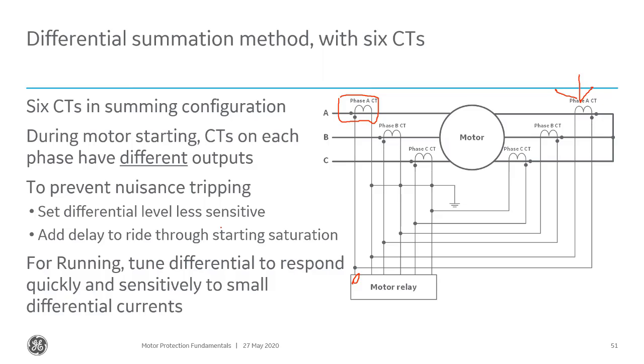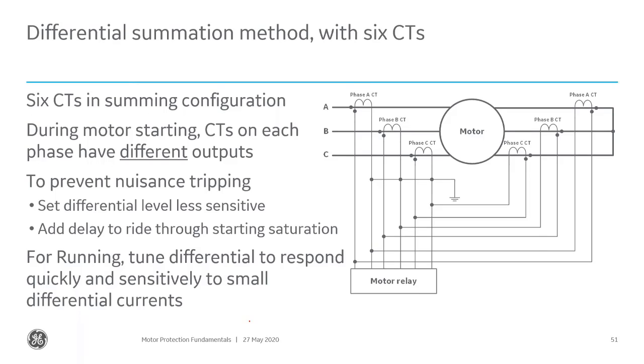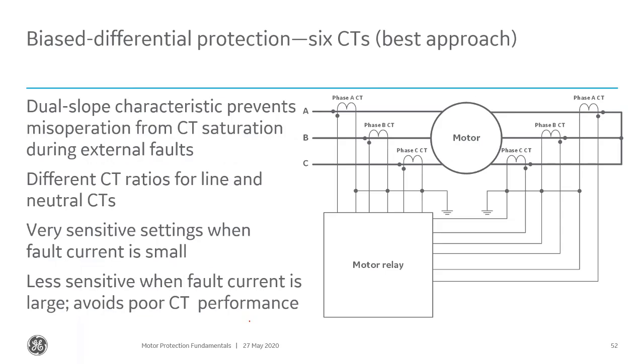The better way actually is the first wiring that I showed, but the other way is this sort of current input, where we wire all the currents individually to the relay. Now, the downside to this sort of arrangement is that it requires an extra set of CTs, right?